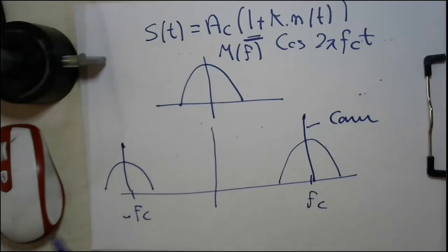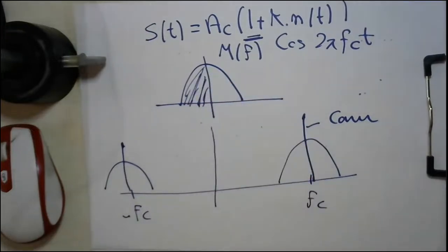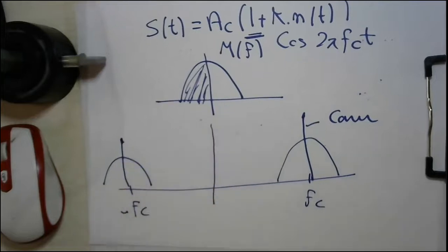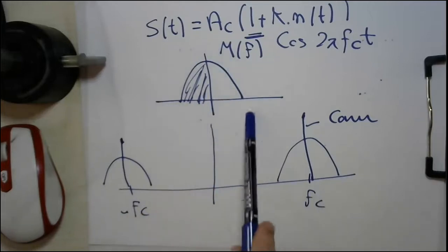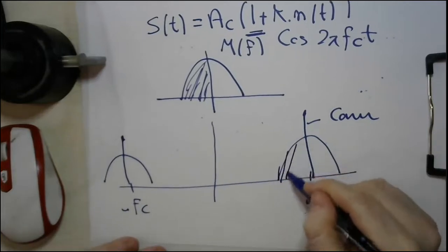When I told you about this portion of the message, whenever we start our lectures, I told you a fact that there is no physical meaning for a negative frequency. And Fourier used the negative frequency just for mathematical description to make his function an even symmetric function around the y-axis. However, when you shift the frequency, when you set this baseband signal to a passband signal, this negative frequency region also has been shifted.